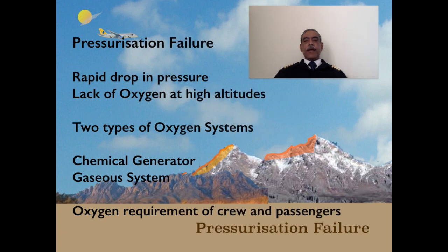In the previous lesson on en route performance, we generally talked more about an engine failure scenario, one engine failure scenario, and the requirements thereof, and for obstacle clearances, etc. But let's not forget that there could be other failure situations which force us to carry out a diversion or to carry out a descent if such failures happen.